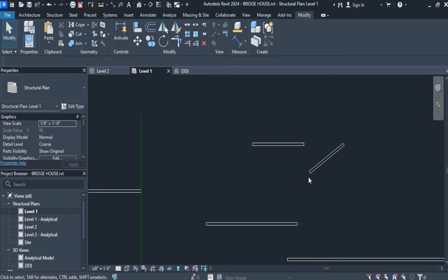So the next command is the split with gap tool or command. This creates a gap between the elements, so still you can edit the options bar and lock the control to be able to heal the walls. This prevents having a wall on top of another.